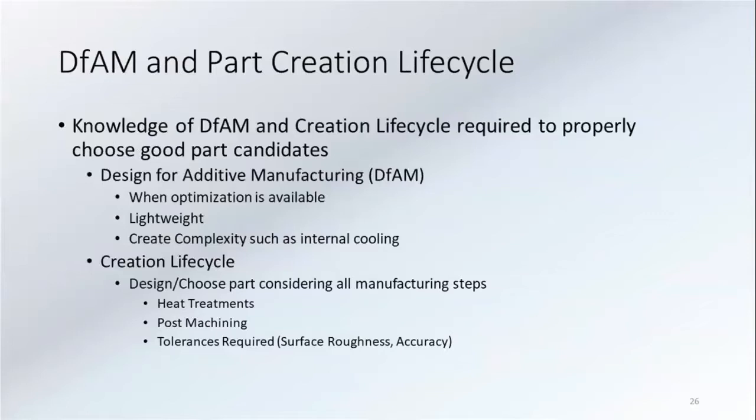Some of the other things you need to consider: DFAM is design for additive manufacturing, and we'll go into how you choose a good part. You're going to look at, can I optimize this part? If I have the freedom to make this part as complex as I want to, then it might be a good candidate for additive manufacturing. If I'm dealing with a reverse engineered part where I need it to be this specific thing, and it's been traditionally manufactured in the past, it may or may not be a good candidate.